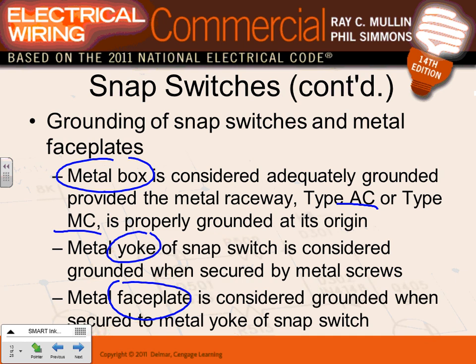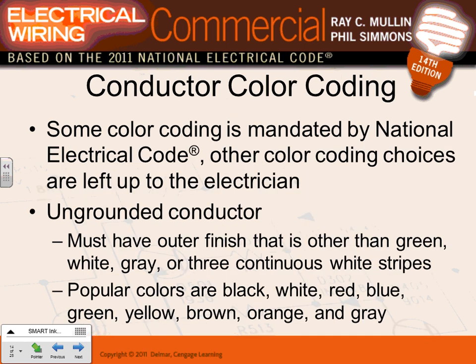Cool? Thumbs up. Most of the time, if it's a non-isolated ground receptacle, they bring a conduit to a box, like you're looking at right here. So now this box is grounded. Can you see that? They pigtail the grounding bar into the box, tied to the box. So now the receptacle is grounded, the cover is grounded, and the box is grounded through the EMT conduit. Cool. So that's the grounding for all these. I know we're not electricians, but it's a good idea to do that.